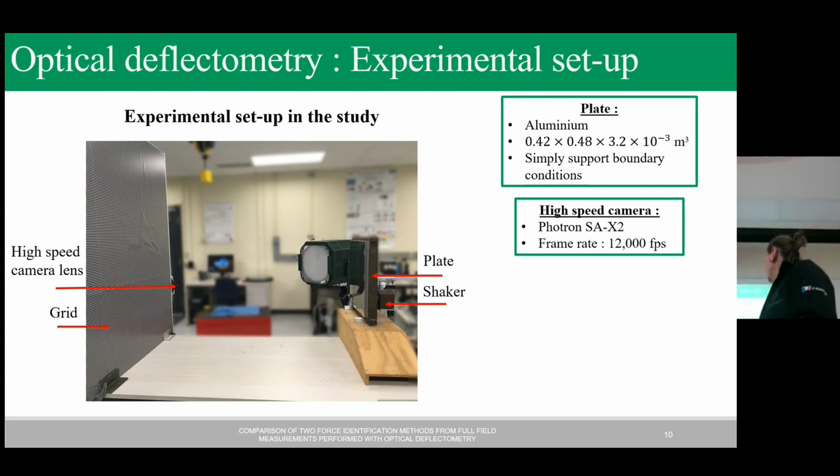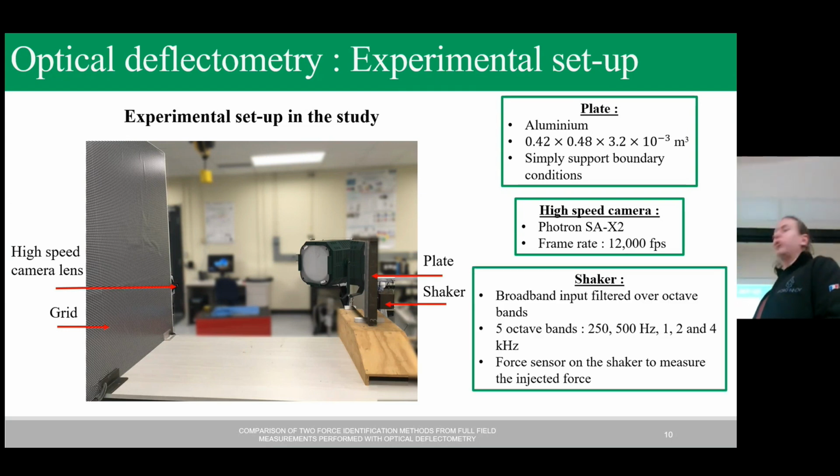The shaker that we used to inject the force in our plate had a broadband input, which was filtered over 5 different octave bands. The force sensor was mounted on the shaker in order to measure the injected forces on the plate.